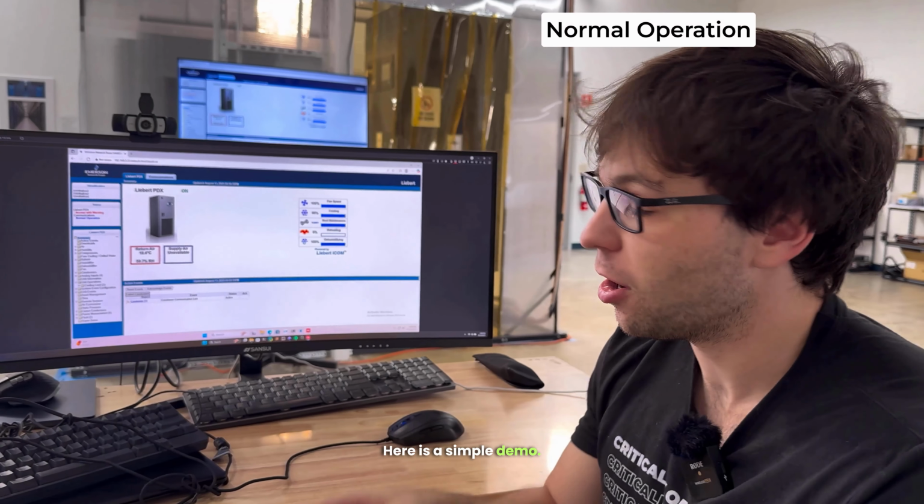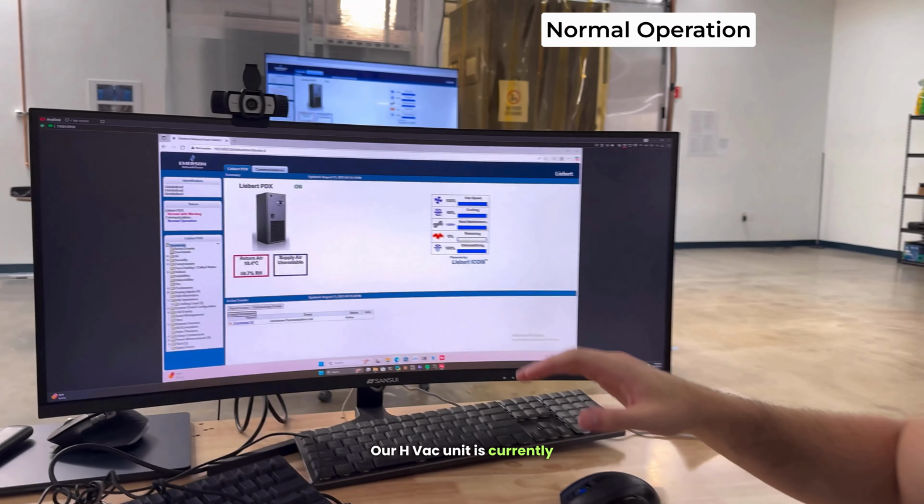Here is a simple demo. Our HVAC unit is currently running at 100% capacity despite being in normal operations, wasting a tremendous amount of energy. As you can see, that fan is blowing constantly, and the compressor is running near 100 the entire time. That's because industry standard HVAC units like this one usually only use their own return air temperature set points, rather than the full knowledge of the environment.